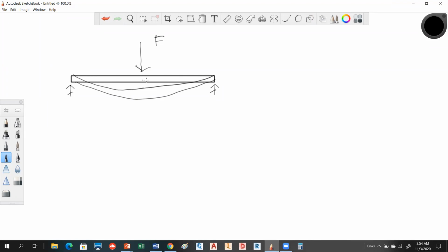And then you've got the other fact there going on is you have shear going on simultaneously. So the two things are one's trying to rip the beam apart, one's trying to deflect it and bend it or rotate it. You guys have all experienced deflection, I'm sure. Have you ever been on a bridge and let's say you're on a stop location on that bridge, you can actually feel the bridge go up and down. Anybody ever experience that on a bridge where it deflects like that? Yeah. And deflection, there are certain amounts of deflection that are legal, if you will.